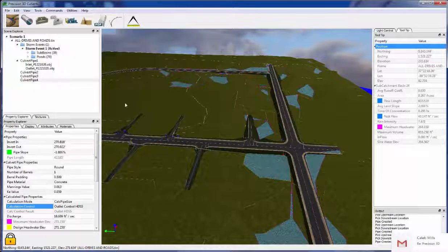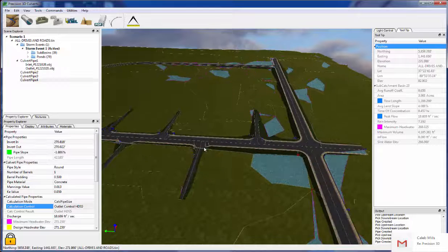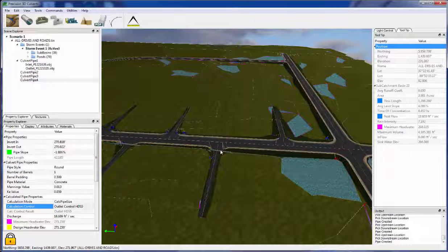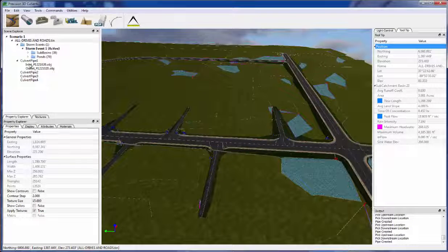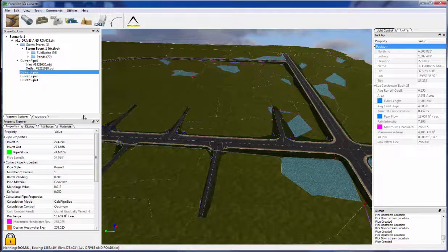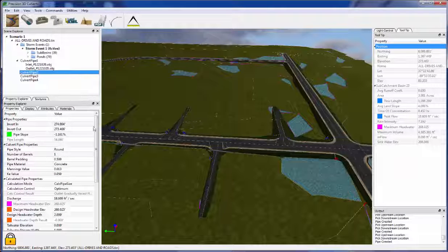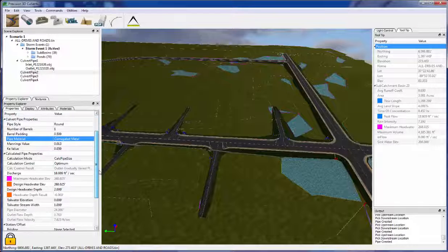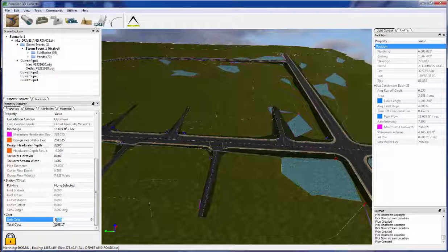And so how did that change the scenario? So I just added these pipes in. And the one thing that we don't have is, since we don't have a super extensive library for cost of materials, when you do change the materials on here, whether it's concrete or CMP, you still need to put in the unit cost for that particular pipe. So every diameter pipe of a different material is going to have a different unit cost. So for this one, I'm going to put $3.